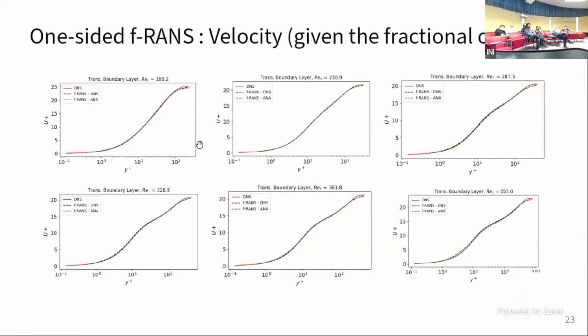And if I have that fractional order corresponding to the right or the wrong expression, since the velocity was DNS, I can invert this whole system and compute the velocity. And I find that for either of the cases, I can match the DNS velocity fields. So that was quite encouraging as a wall model. This one model can generate velocity profiles for both transition as well as turbulent cases.